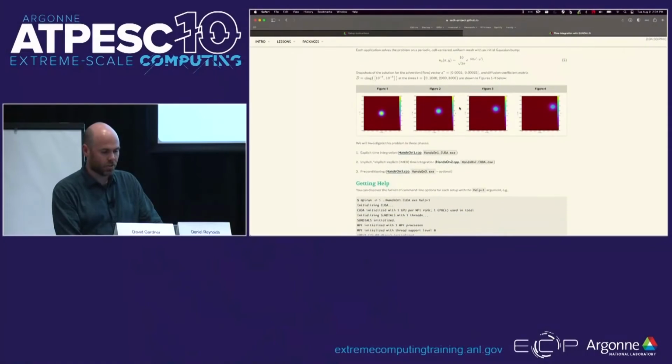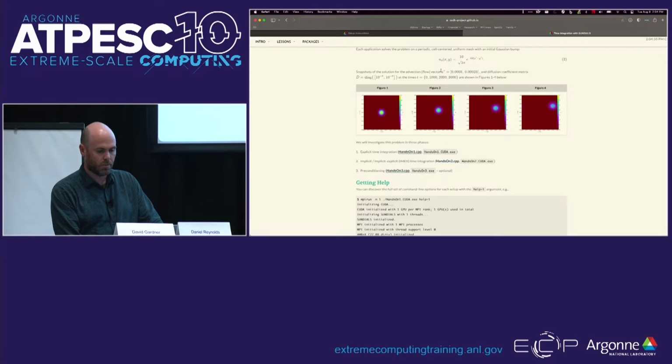Specifically, we're going to use the ARKODE package out of SUNDIALS, which does explicit, implicit, and IMEX Runge-Kutta schemes. We're going to start out with this initial Gaussian blob and drop it into a field where there's this particular flow and these diffusion constants. You're just going to see it travel up and to the right, advecting along and also diffusing out.